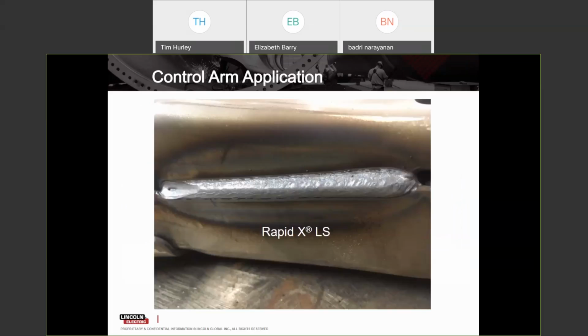So what this definitely told us was that we have a specific alloy content which has been tailored to the base material composition for the shielding gas that was required by the customer and tied to a particular waveform, which is a Rapid XLS waveform, which gave us the best combination of electrode, base material, and waveform procedure for giving the lowest silicon island performance.